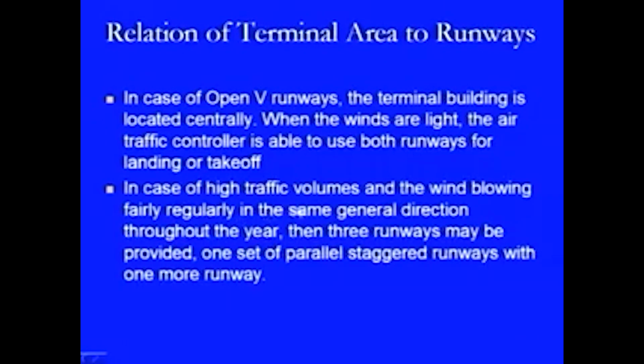In case of high traffic volumes, and if the wind is blowing fairly regularly in the same general direction throughout the year, then three runways may be provided: one set of parallel staggered runways with one more runway. So, that is the way we can handle the conditions arising at any airport out of varying traffic volumes or meteorological conditions, especially in terms of wind durations, intensities or directions.